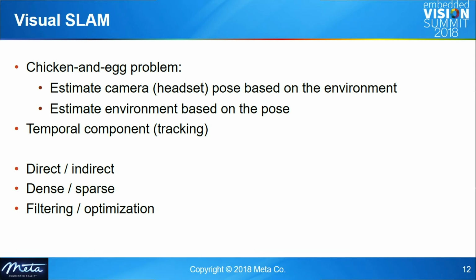So that's the first important two camps in SLAM. Dense versus sparse means whether you use the whole image or only parts around some key points for matching. And lastly, filtering versus optimization means how you optimize for the pose. Filtering, typically different variants of the Kalman filter, uses a filtering approach, and in optimization you usually do bundle adjustment to optimize for the camera poses.